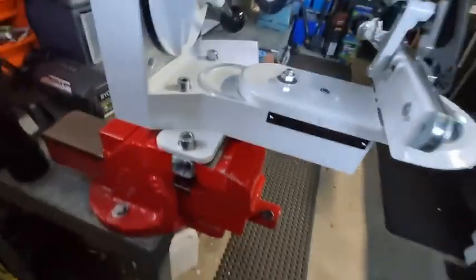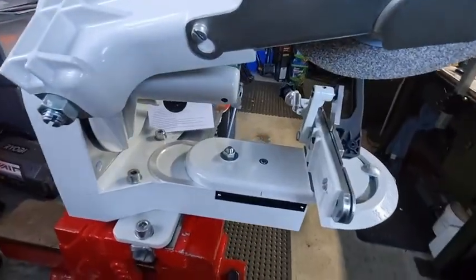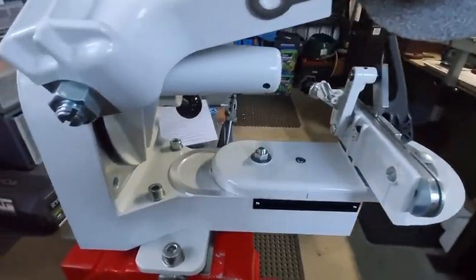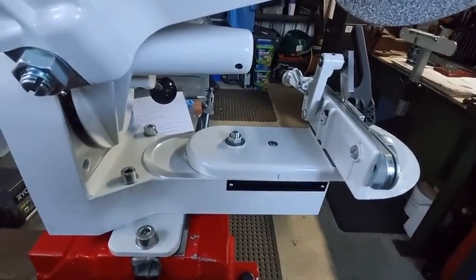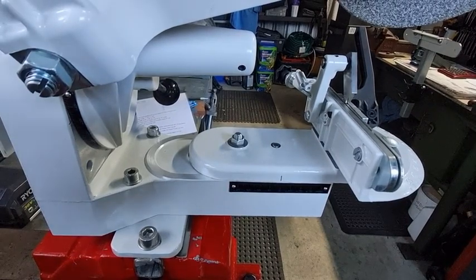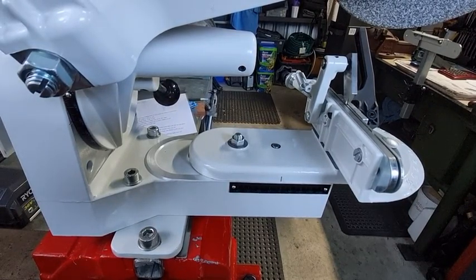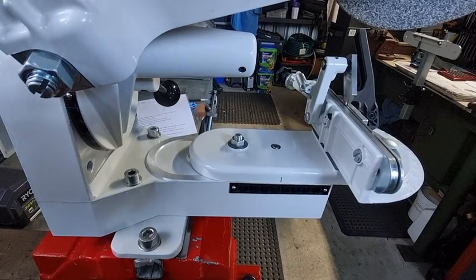It's not in, like they turn around and say 10 degrees. So obviously Stihl don't recommend the 10 degrees downward tilt. Going back to the days of the MS660, probably around 1990, it was in the Stihl manual that 10 degrees downward tilt was recommended, but I think they've slightly changed the height of the tooth, of the geometry since 33 years ago. Still don't recommend it, but I still recommend using a 10 degrees downward tilt, or even a 5 degrees downward tilt.